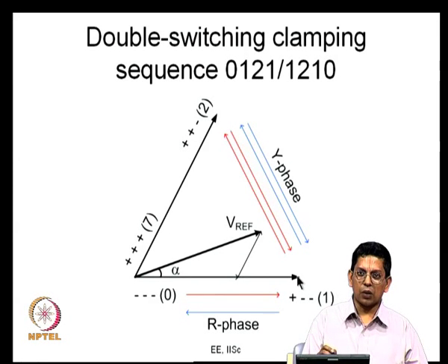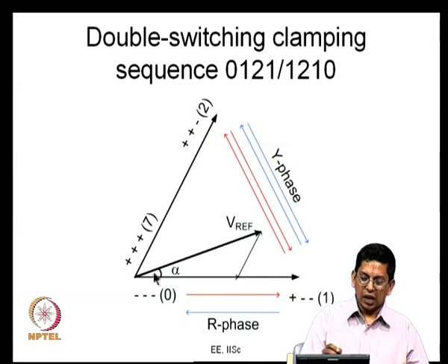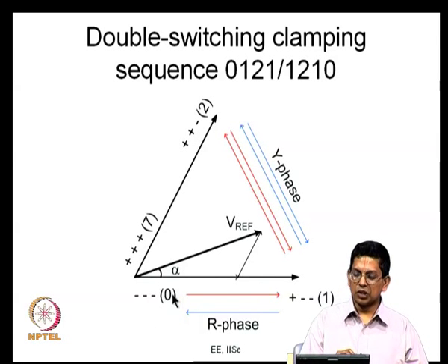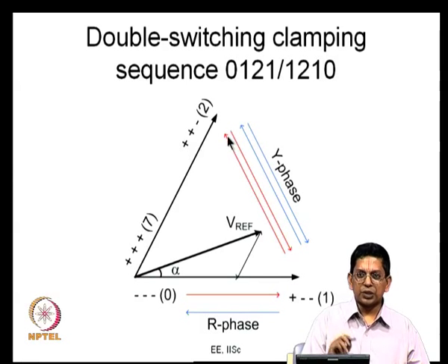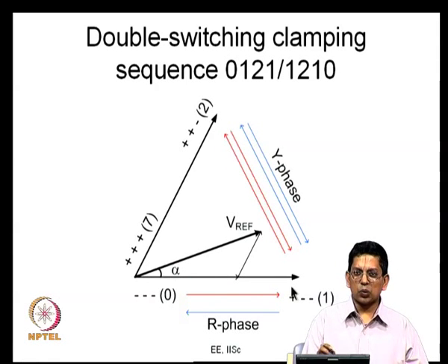So, that is the answer, because from the space vector domain you know that you have to apply active vector 1 for t1 seconds and active vector 2 for t2 seconds and the null vector totally for tz seconds. So, it does not matter in what sequence you apply; you have to move in a particular sequence so that you do not switch unnecessarily. You see that every transition you are switching only one phase and changing from one state to another. Here only R switches, here only Y switches. For every state transition only one phase switches, other than that we are not doing anything. So, now it is totally 3 switchings. We are avoiding B phase switching and we are switching Y phase twice.